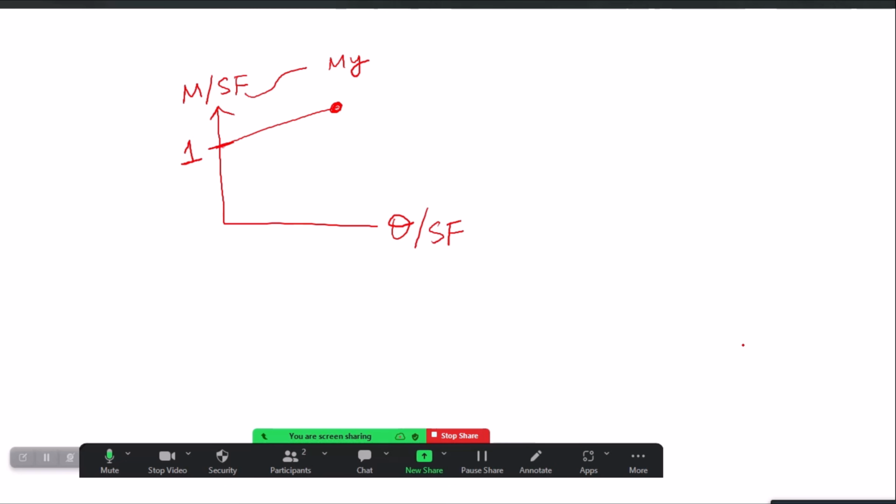Maybe like 1.2. If I just put 1.2 here for this point, it means that I have a 20% over strength in my beam up till the ultimate point. Then it goes down and then it becomes flat and then it becomes exactly 0, joining the x-axis. The scale factor for the x-axis can be 1 because I directly want to start my curve from the yield point. So this point is already my theta y, right? My origin is already theta y.